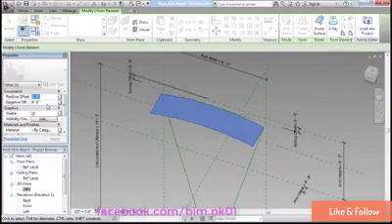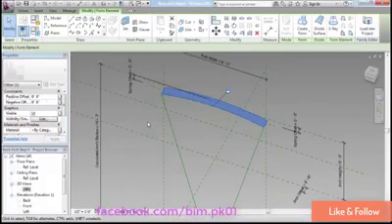So we're going to go ahead and just dial in some direct numbers in here. I'm going to put in a negative offset of 8 inches and a positive offset of 0. And when I apply that, you're going to see the arch actually shift the other way. So I'm using the curve at the leading edge here as the front of the arch, and then having it go 8 inches back from that point.